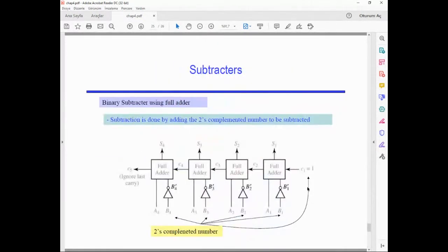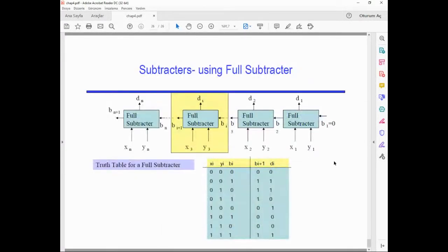Also you can have the subtractors by just flipping one input, like A subtract B. It means if you get NOT B, you can get the subtractor, not the adder. The opposite of adder means subtractor, right? You can get the subtractors just by using one NOT gate. We will do this example with Logisim next Monday.